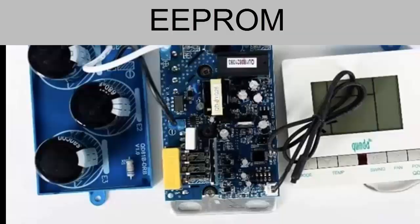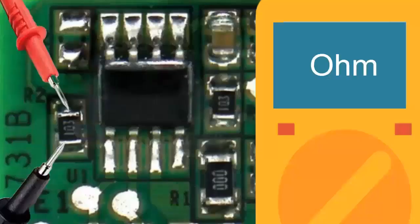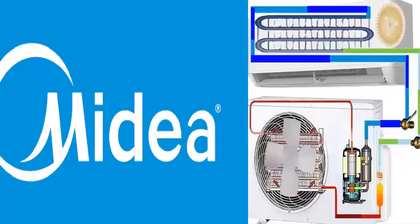1. Locate the EEPROM and the controller on the board. The EEPROM is a chip usually featuring 8 pins, arranged in 4 pins on each side. 2. Inspect resistors near the EEPROM. Check the resistors around the chip. If any resistor shows an unusual value, replace it. 3. Verify the condition of the EEPROM. If the EEPROM is damaged, it must be replaced with a new one containing the correct programming or one extracted from another board of the same model.